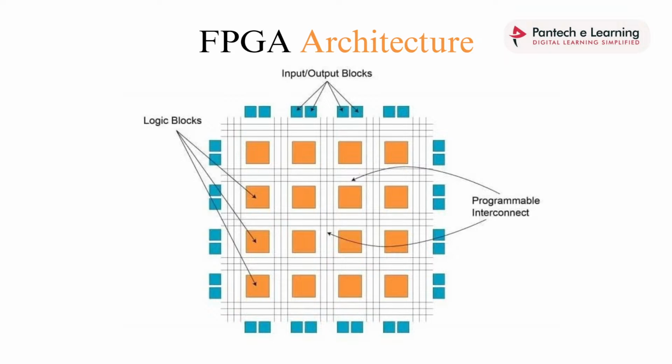And this is the architecture of the FPGA. This FPGA consists of lots of blocks like IO blocks, logic blocks, programmable interconnections, RAM blocks and DSP blocks. There are many more blocks in a single FPGA. The logic blocks consist of RAMs, DSPs and PCI Express also. The fabric and all the parts make the FPGA a heterogeneous computation platform, because all these computer resources can be accessed at the same time. You can access all the logic blocks at the same time, and you can access specific logic blocks.